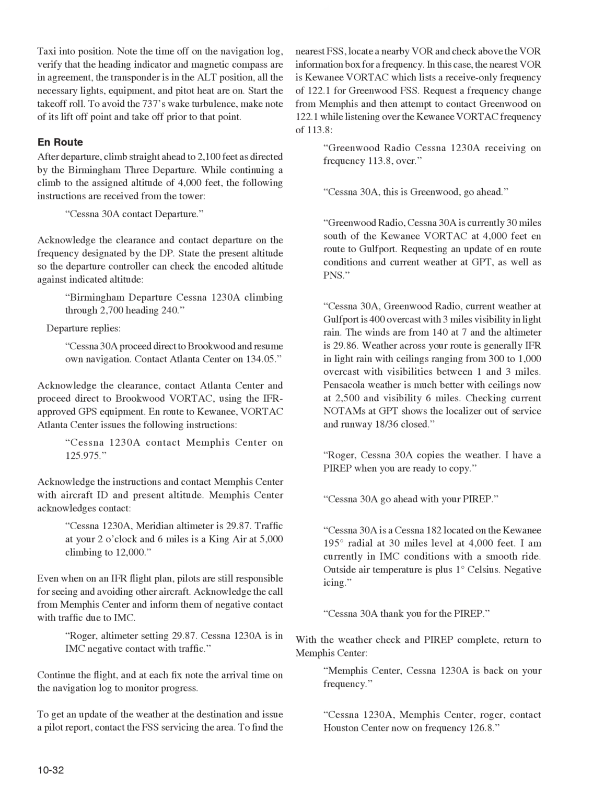En route to Kewanee VOR, Atlanta Center issues the following instructions: "Cessna 1230A, contact Memphis Center on 125.975." Acknowledge the instructions and contact Memphis Center with aircraft ID and present altitude.